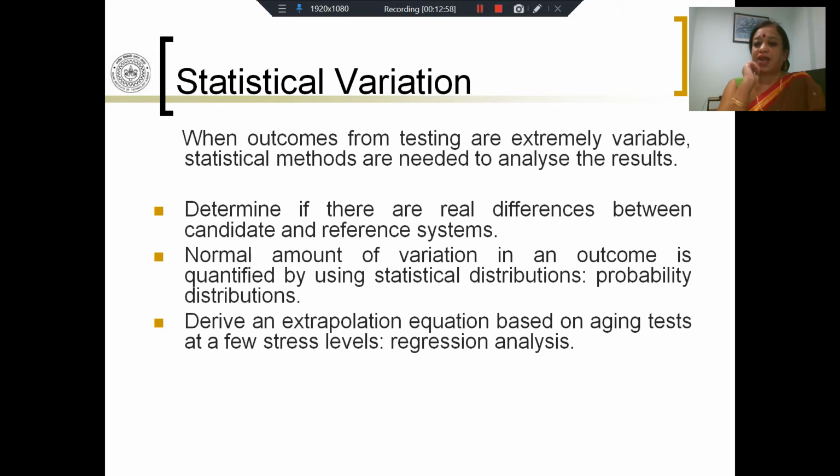You have a nanodielectric and you are using epoxy. And you think it would be a good idea to use the nanodielectric instead of the epoxy in applications where you already use epoxy, maybe bushings. So if you apply a particular voltage, you expect the epoxy to, let's say, break down at 38 kV per centimeter. It is not essential that it is going to break down at 38, it may break down at 50 kV per centimeter, whereas the nanodielectric you have designed, you expect to break down at 50 kV per centimeter, but when you apply the voltage, it may break down at 30 kV per centimeter. Does that essentially mean that the nanodielectric is not better than the epoxy?